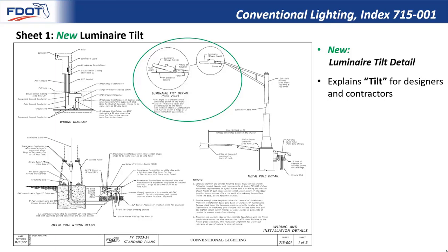And so the luminaire tilt is a fairly common term for those that are familiar with the design process, particularly when using software like AGI32. But it turns out that some folks that are new to design and some contractors had some issues with envisioning how this luminaire tilt was supposed to look. And so contractors and installers that wanted to insist that their installation was okay as is really had no definitions or drawings to take a look at to ensure that they were doing it correctly. So as a result of that district feedback, we've added this detail.